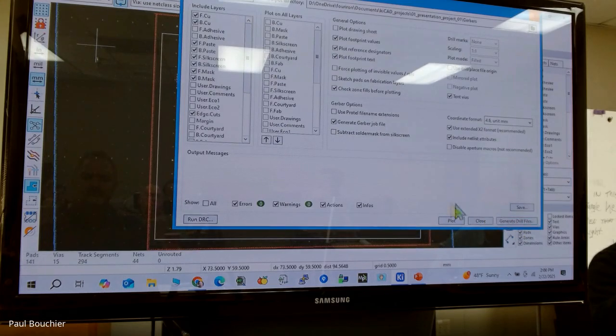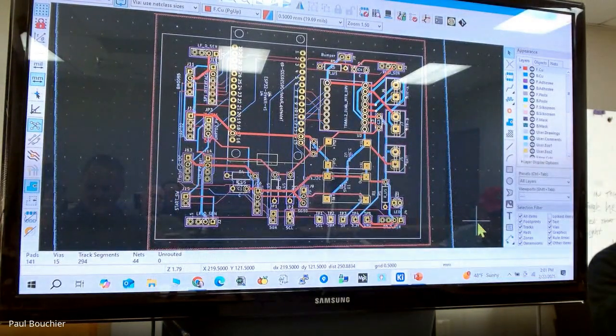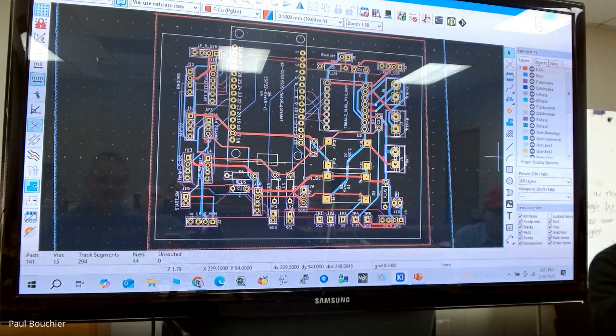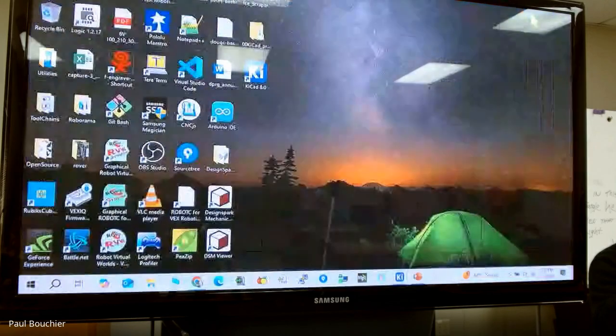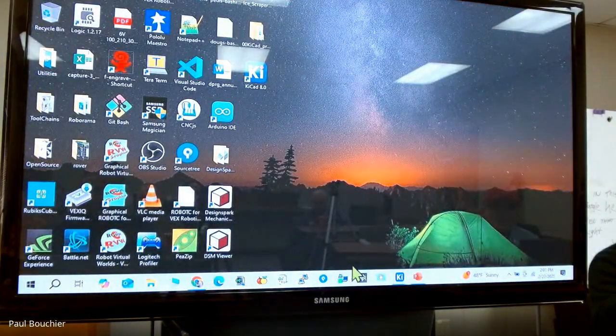When you do generate drill files, it's going to open up another box, and you're going to have to do a drill map and a drill file. So you're going to do all of that. Now, this is how you do it. Well, it won't, because it wants to go to OneDrive. Okay, your project. Yeah, so just close it. Now, if you go to project 1 and look in the Gerber directory, you should see some files. They're not on OneDrive, they're there. Okay.